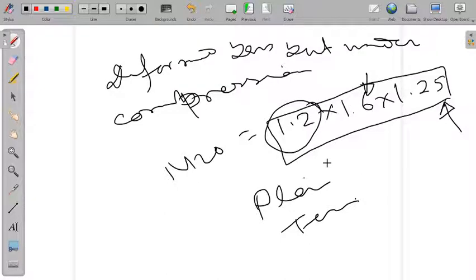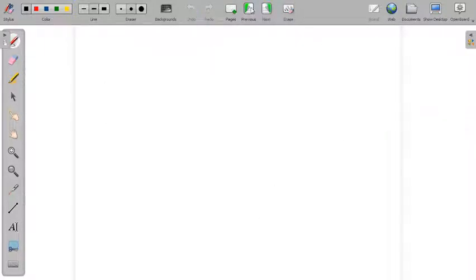Once we know the bond stress, then we can find out the development length required. So what is the development length? Let us know that first, then we will see how the development lengths are calculated. Let me tell you. Basically, a tension member has to be anchored properly by providing additional length on either side of the point of maximum tension, which is known as development length in tension.